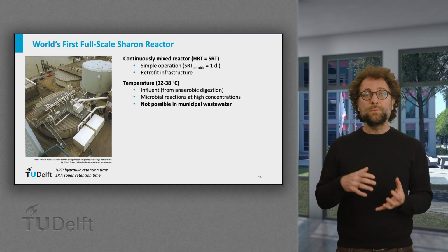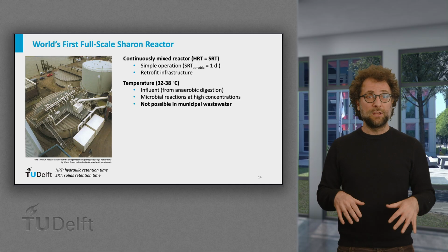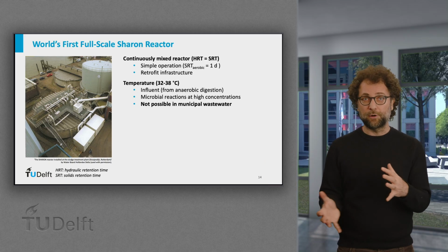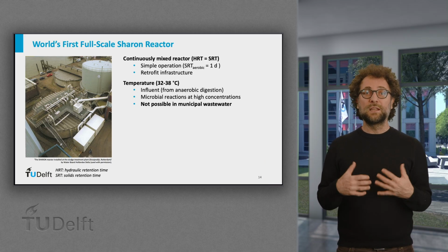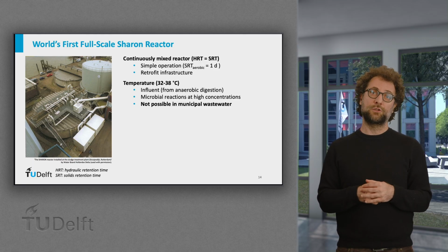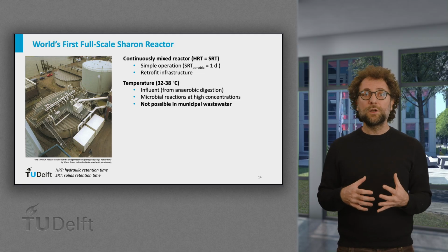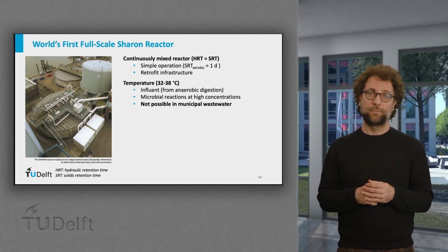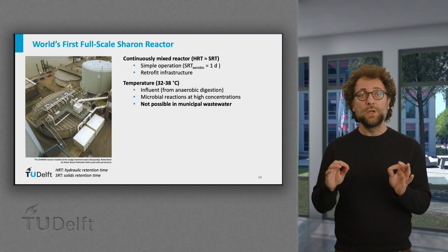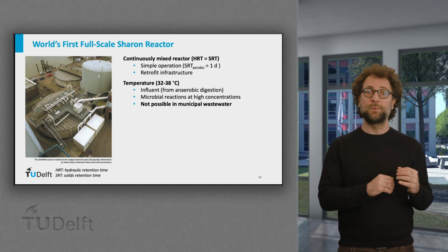The temperature is maintained between 30 and 40 degrees Celsius, thanks to the influent temperature coming from anaerobic digestion and the significant biochemical heat production due to the high inlet concentrations. In fact, the reactor often requires cooling. An important consideration is that operation at high temperature is not possible directly on municipal wastewaters.